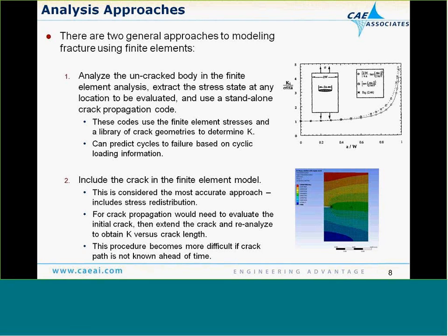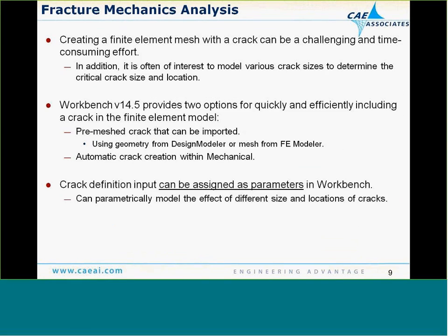But the problem is, if you want to start modeling the crack propagating, we don't always know ahead of time where the crack's going to go, and you're going to have to have reasons or techniques to figure out which way the crack's going. So it's not a trivial thing to put a crack in a model. Even if you know where the crack is, to model it is not trivial, because you have to split the geometry, change the mesh, and do stuff at the crack tip and so on.